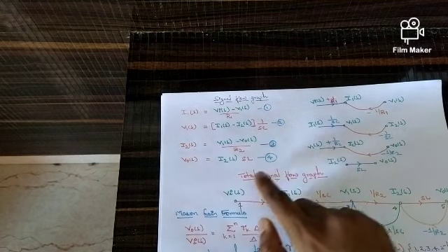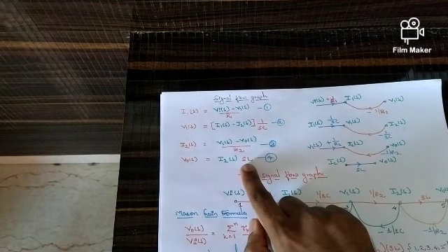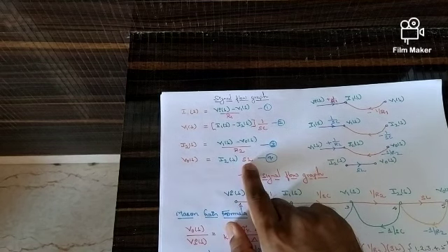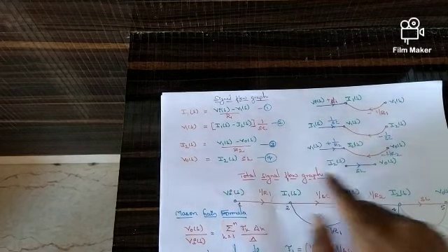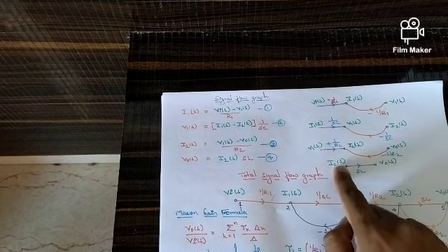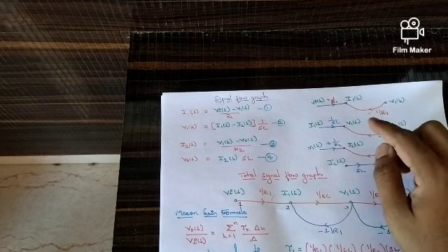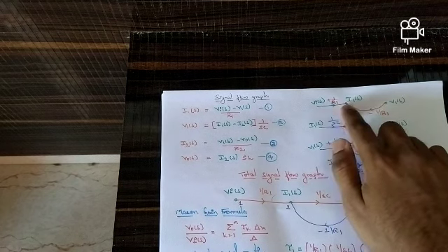Again, V0 of S, we don't have any feedback here, there is no negative sign, so it is I2 of S, and SL is the gain. So V0 is the output, I2 of S is the input, and SL is the gain. Now from this you can easily see that I can write this part easily.